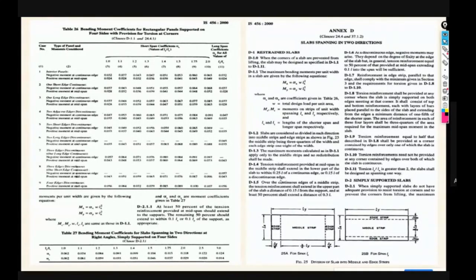If any slab is there, whatever slab, 2-inch, 5-inch, 3-inch, 9-inch, whatever wall you are providing, we should consider a beam below the wall, as a structural point of view. Yes, in some cases such loading may come, but actually it is not allowed from a structural point of view. And if you refer to any book, such a design you cannot find.